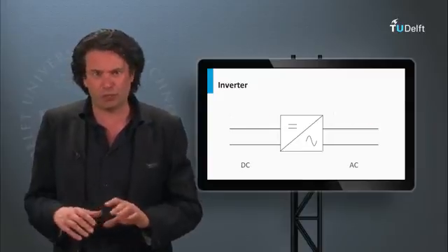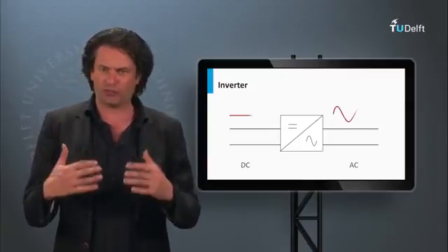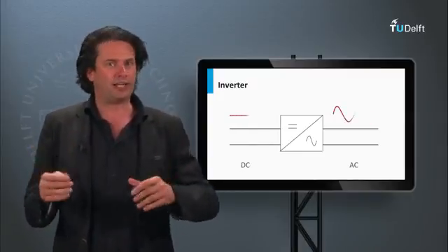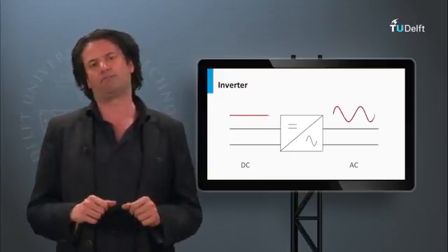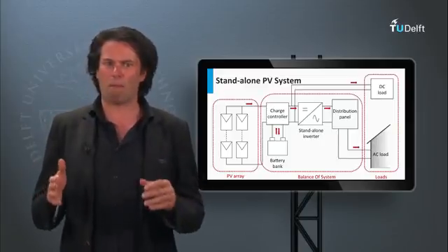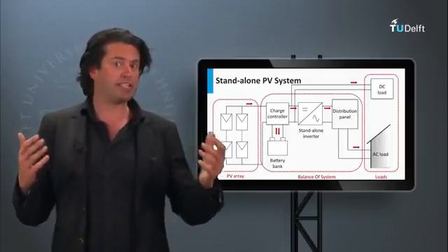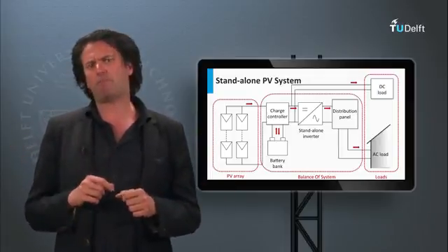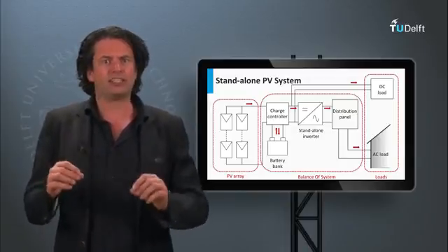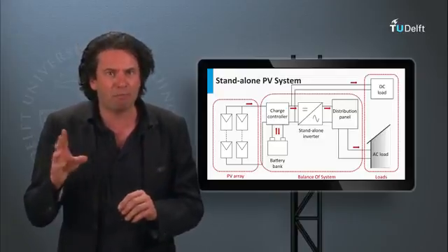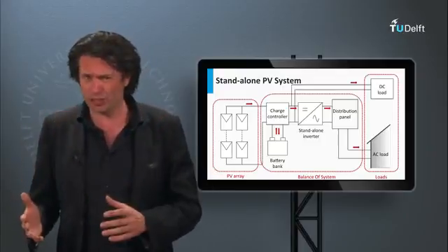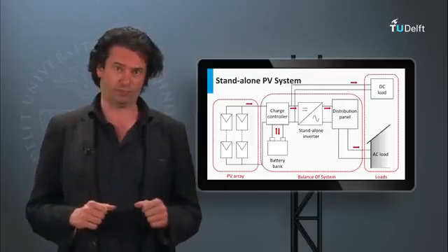Given the time constraints, we will not go into the internal circuitry of the inverter, but we will talk about the features of the solar inverter and its application in the modern PV system. Now, inverters could be classified based on their size, mode of operation, or implementation topology. Here I will talk about the classification based on the mode of operation. Under this, inverters can be classified into three broad categories: standalone inverters, grid-connected inverters, and bimodal inverters.